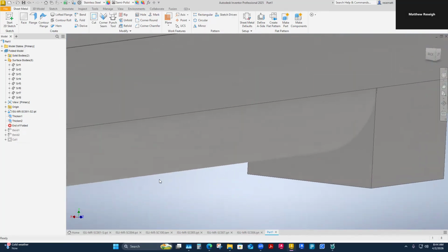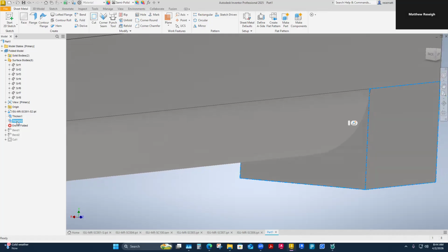And so what I chose to do was go back into this command. Remember, I don't really want to delete it and start it fresh because it is driving a part underneath me. We've already created the part from it. So if you start deleting this stuff, that part disappears. It's not the end of the world if you do that, you can always resend it to the assembly. But here, if I can prevent that, maybe it's easier. And there's parts of this that I want to keep. I just want to not do them all as the same thicken command.